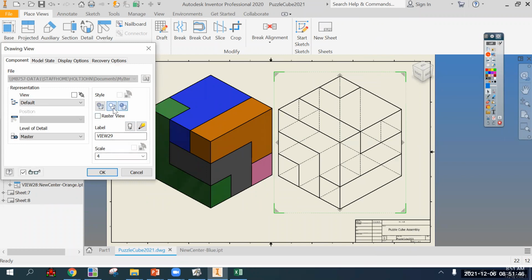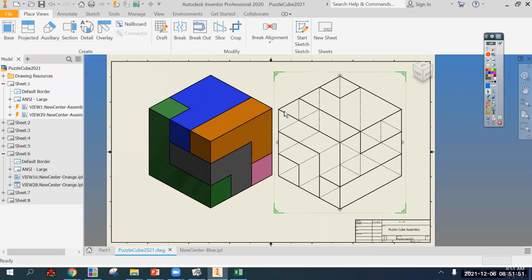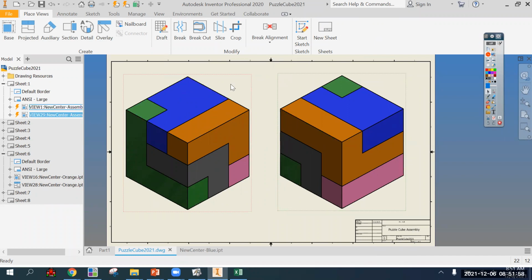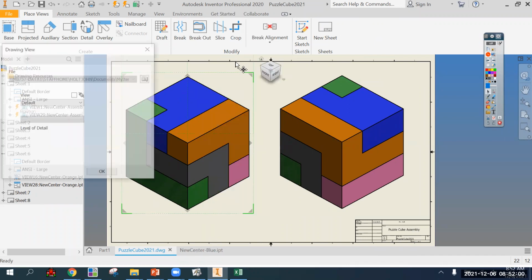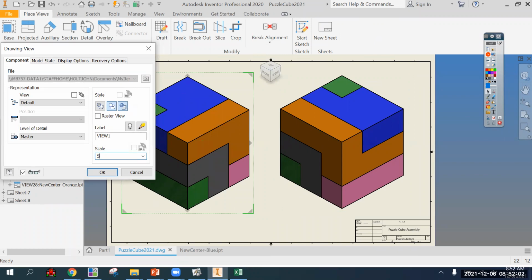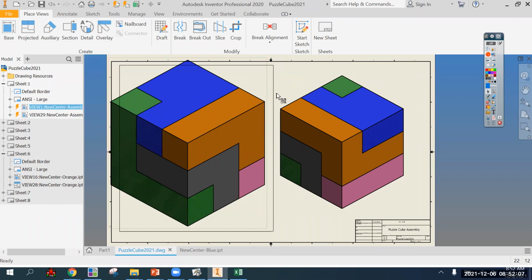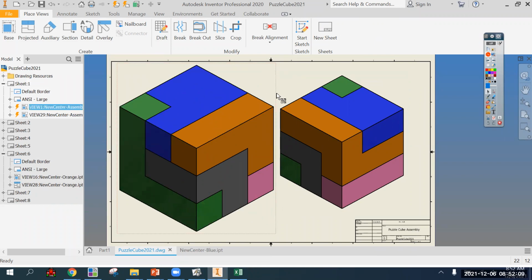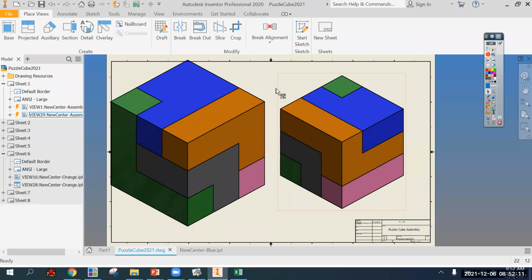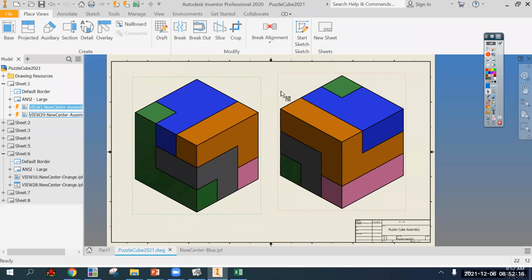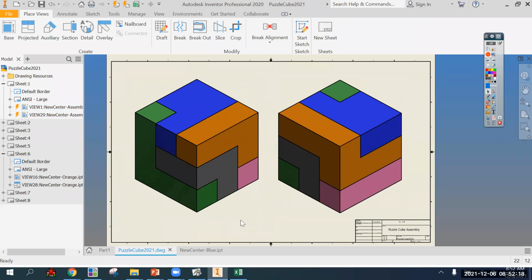Turn on solid or hidden line removed and shaded for these. 4-to-1 seems a good scale also, but you don't want it to barely fit in the space. And even though I'm pretty sure I could get a 5-to-1 to fit without crossing lines, you don't want it to be crowded. You want to use the space without crossing over lines or feeling crowded. And that's just an aesthetic thing.